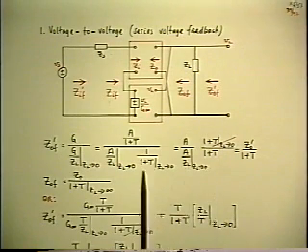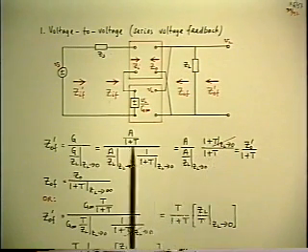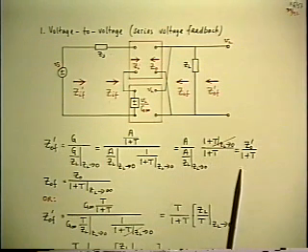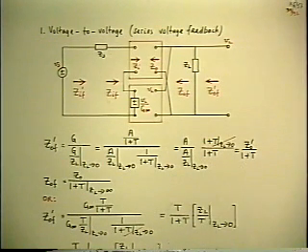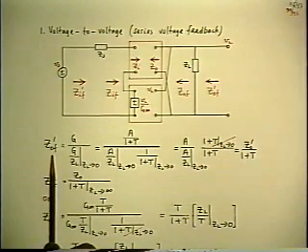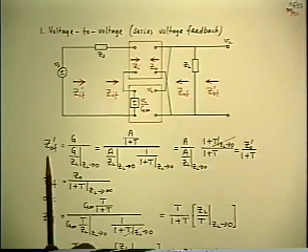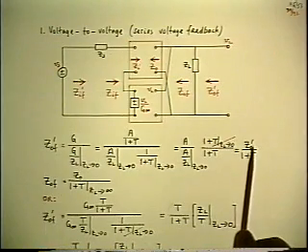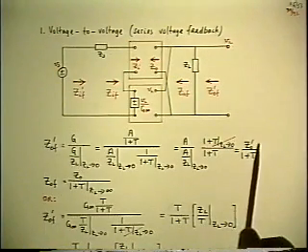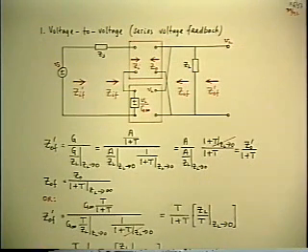Well, what else is left? Just the 1 plus T that came from the numerator. So that's the result. And it's a well-known result. You know it already. What it says is the outside output impedance of the amplifier with feedback is equal to the outside output impedance before feedback divided by the feedback factor. The same factor by which everything else gets changed.